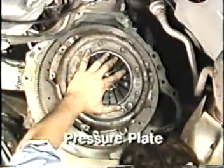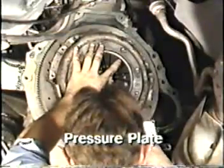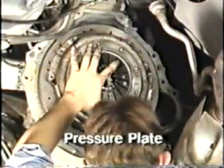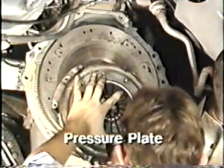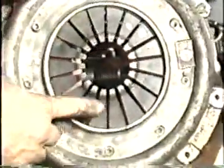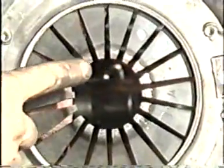Next, inspect the pressure plate. The pressure plate clamps the clutch disc to the flywheel, transferring the engine's power through the disc to the input shaft of the transmission. When the release bearing presses against the release fingers on the pressure plate, the clamping pressure is removed, disengaging the clutch. It's important to check for release finger wear. If the fingers are worn, the clutch may not fully release. Be sure to inspect the face of the pressure plate to see if it's been burned or worn.